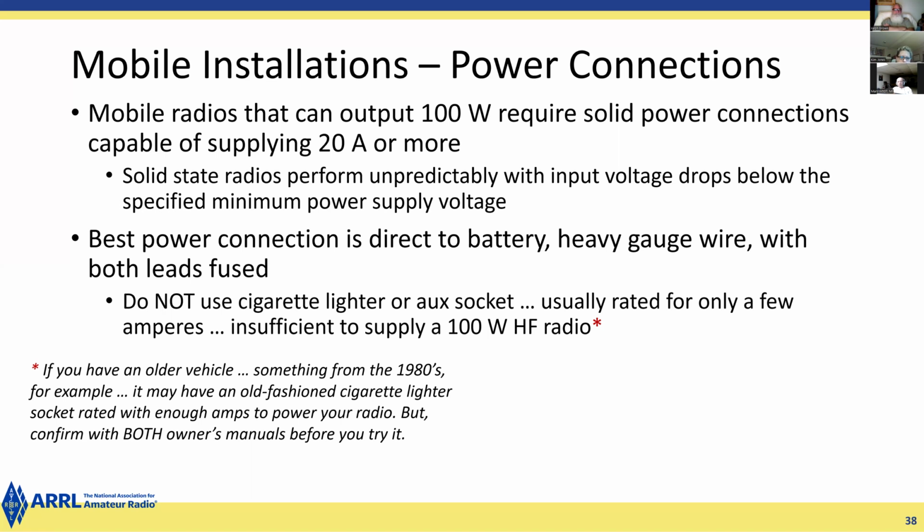So if you're adding a 100 watt transceiver, and you only transmit part of the time, you're probably okay. You're probably not going to run down the battery, but you have to be very careful about two things. One is that you don't run into problems with the battery running down. And the other is that when you turn off the radio and the ignition is off, the radio is not drawing any current at all.